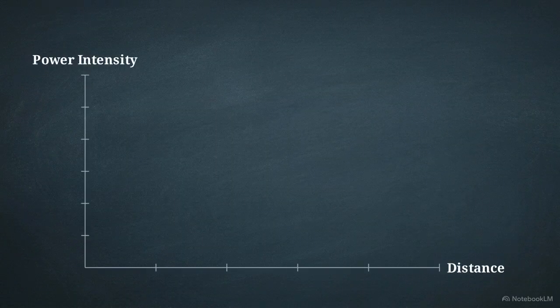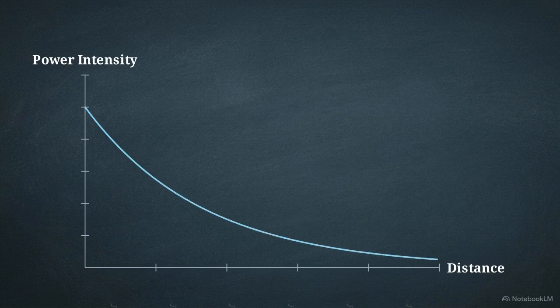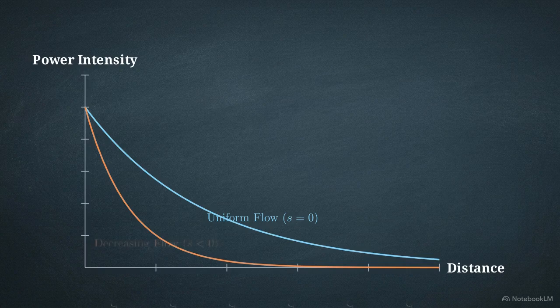This chart maps spatial decay. When the power transfer constant is zero, we see uniform power flow. Energy drops strictly according to baseline dissipation. If the constant is negative, power drops off much more sharply, decreasing spatially faster than baseline. In this negative state, the wave leaves energy behind, supplying power to line elements and slowing overall temporal decay.